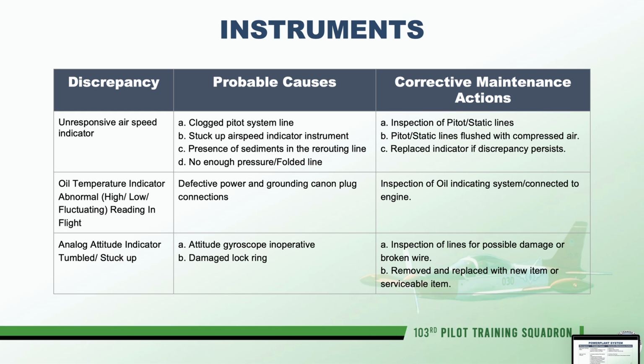For abnormal oil temperature indications, the issue could stem from a faulty sensor or wiring. Inspect the oil temperature sensor circuit for any signs of damage or corrosion. Grounding issues: poor grounding or loose power plug connections can lead to inaccurate readings. Ensure all connections are secure and clean. Sensor connector replacement: if the sensor is defective or the connector is corroded, replace them to ensure accurate temperature readings.